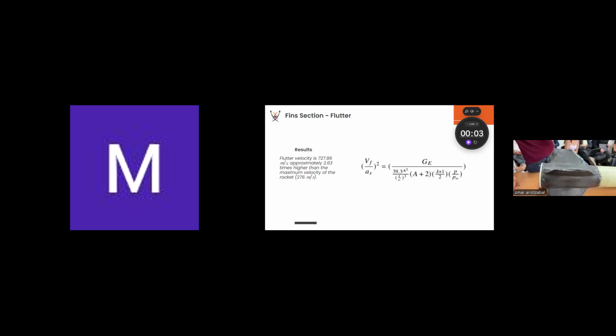Number one, you're using an airfoil, so it's not a flat surface. And then number two, you can't use this equation with something that has a multi-dimension, right? This equation assumes a flat surface throughout the width of the fin. So you need to annotate here that you use the average thickness for this particular calculation simply because you have an airfoil and therefore this equation can't be used.